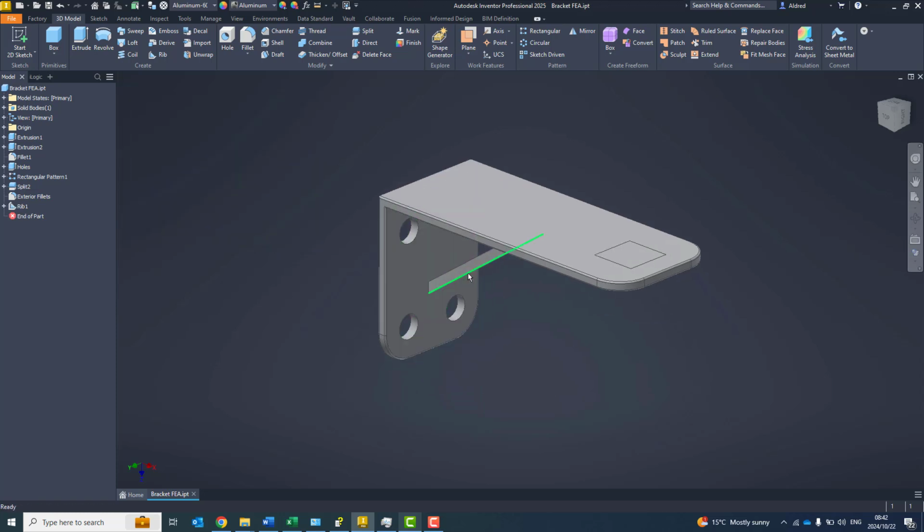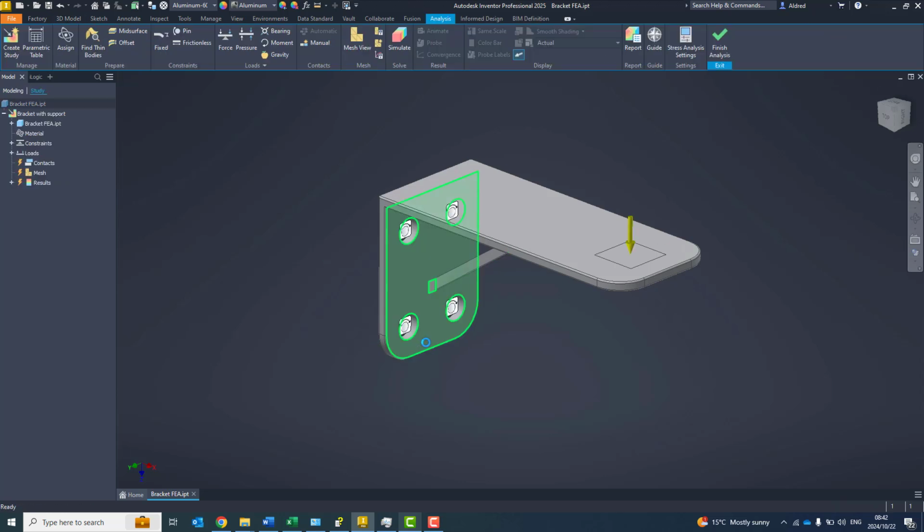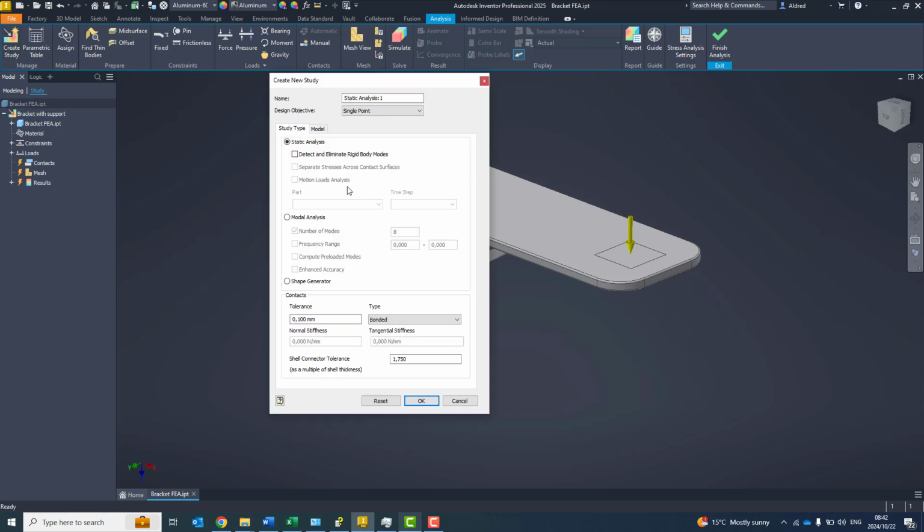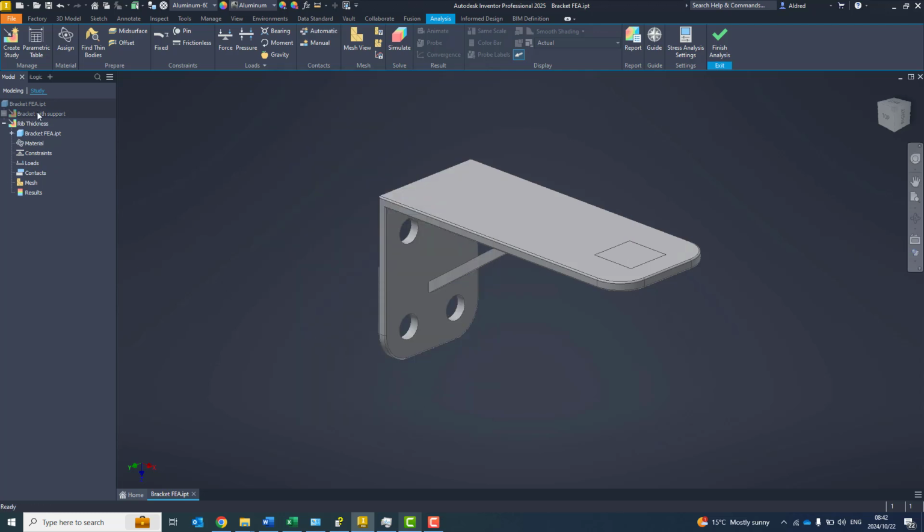Okay. So now that that's there, I can go to my stress analysis and create our study. So let's go create study, and at this point I'm going to say rib thickness, and I want a parametric dimension study. Let's go OK, and you'll see it over here.